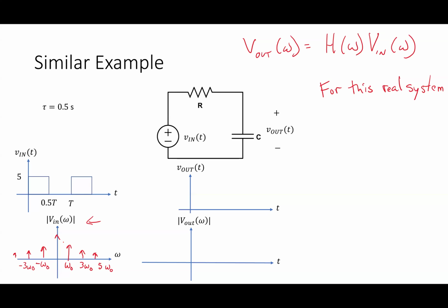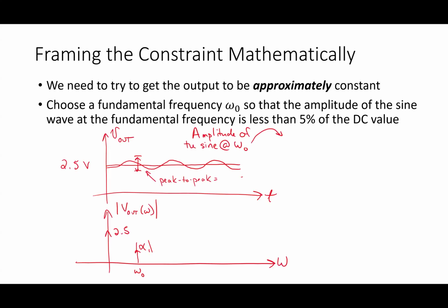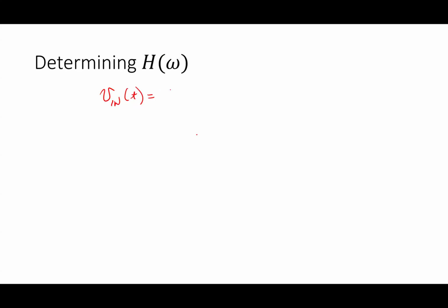All right. So let's just real quick, we walked through this the other day, but just as a reminder. Let's say I have this differential equation: tau dv out by dt plus v out. I want you guys to help me out to figure out the Fourier transform. How do I get to the H of omega from this? I take the Fourier transform of both sides, right? So what happens when I take the Fourier transform of both sides of this thing? What do I do with the v in of t? What do I replace that with?